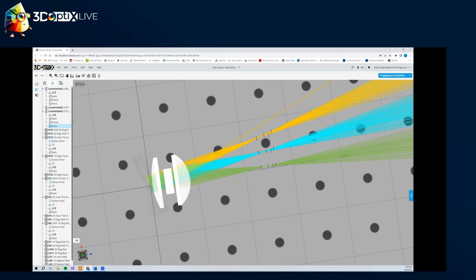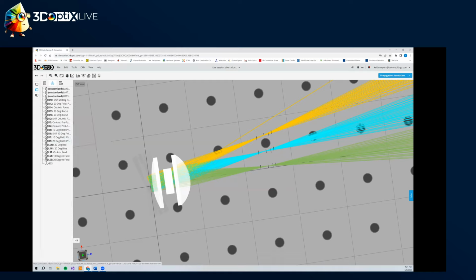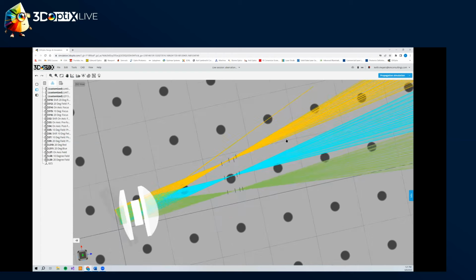If we're really wanting to know where the light is going every time it hits an optic, we can do that with this feature. Again, this is a really nice feature, so we can easily see how our beam is propagating through the system. So we're going to go ahead and remove that. So hopefully that is useful to some of you. I know it is useful to me if I don't want to put a bunch of detectors everywhere in my system. If I just quickly want to see what's happening, I can use a couple surfaces as detectors and use the analysis on that.